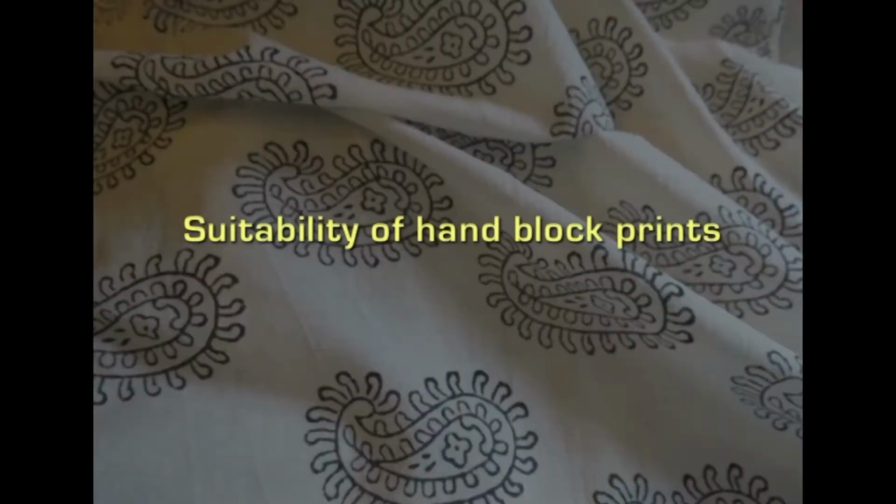Since the block has to be lifted and stamped on the cloth repeatedly, its size as well as its weight should not be excessive, so that it can be manipulated easily. Each fresh portion of the cloth has to be printed by a separate application of the block, and the successive impressions have to be adjusted accurately to each other. Coming to the suitability of hand block prints, today fabric is block printed only in comparatively short lengths of material. Block printing is found chiefly in decorative pieces for the home or inexpensive linens for upholstery purposes.